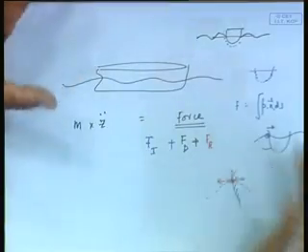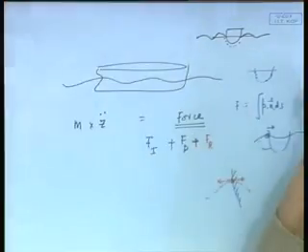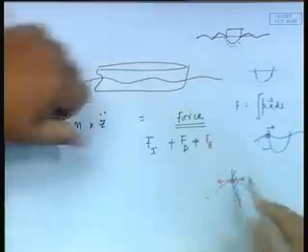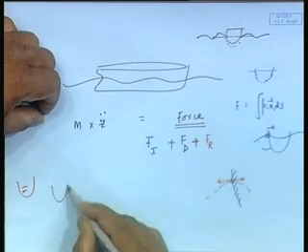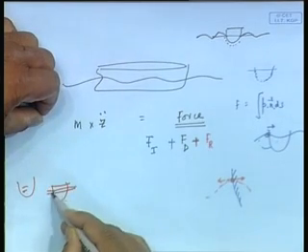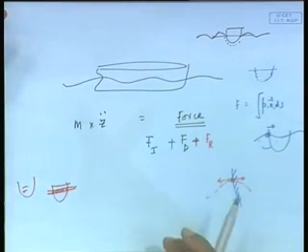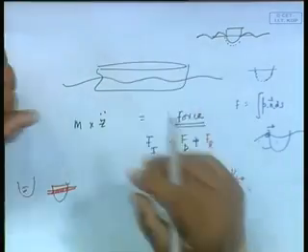Remember also that there is hydrostatic pressure, because if I were to take the shape from here and push it down to this much, this extra hydrostatic pressure comes in. So there is a hydrostatic force also. My shape has a static draft of 10 meters. If it went down to 11 meters, I have that rho g AWP into that 1 meter pushing it up. That's coming purely because of the hydrostatic pressure, rho g z. So there is another hydrostatic force.